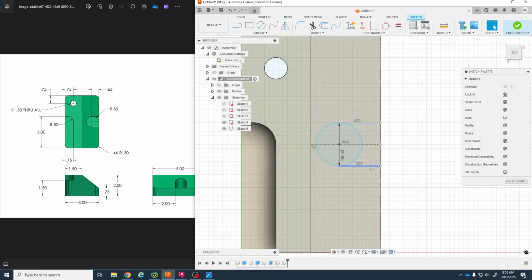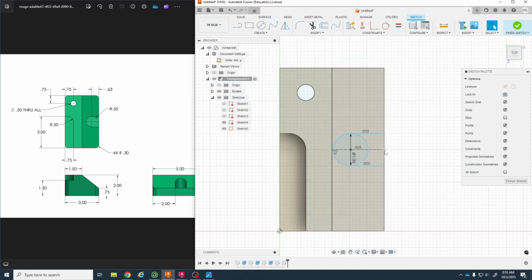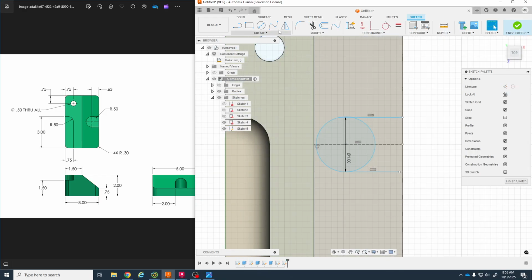Yeah. So wait, where'd you make the midpoint line at? Just in the middle of the line? Yeah. I was able to snap in the midpoint. This little triangle means midpoint. But you could just make a line randomly and then just do a dimension from here to here, and as long as it says 2.5, it's in the middle, right? Okay. All right. From there, I'm going to trim this part and this part off and then close the sketch